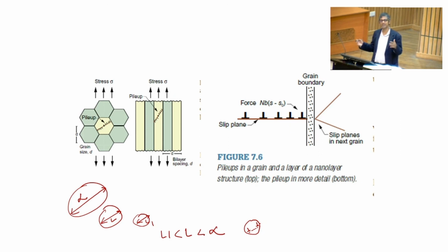If no stress is acting on the grain boundaries, their action as an obstacle doesn't make any sense, okay? Because the amount of stress applied on the grain boundaries will be much smaller. Even you can have a grain size which is much smaller, where you can only have 1 dislocation. There, this dislocation is comfortably sitting inside the grain without even interacting with other dislocations. So therefore, there will be no force acting on the grain boundaries.